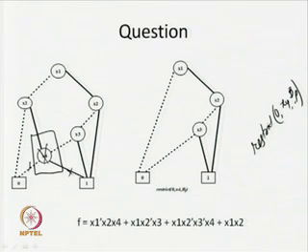So, these two will be removed. And now, we are going to restrict x4 to be equal to 0. So, all incoming edges to x4 should be redirected: this dashed line is redirecting to 0, so it will be redirected to this particular 0, and the solid line will be redirected to this particular 0. So, after removing this portion, we are getting this BDD.